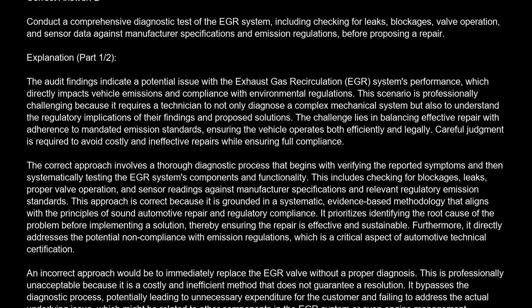The correct approach involves a thorough diagnostic process that begins with verifying the reported symptoms and then systematically testing the EGR system's components and functionality. This includes checking for blockages, leaks, proper valve operation, and sensor readings against manufacturer specifications and relevant regulatory emission standards. This approach is correct because it is grounded in a systematic, evidence-based methodology that aligns with the principles of sound automotive repair and regulatory compliance.